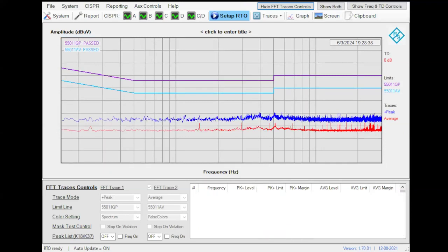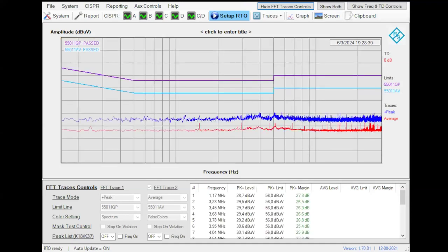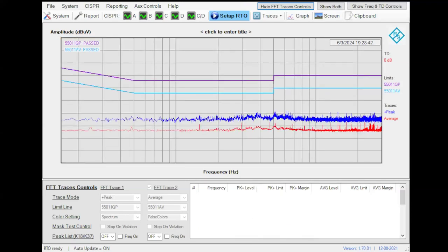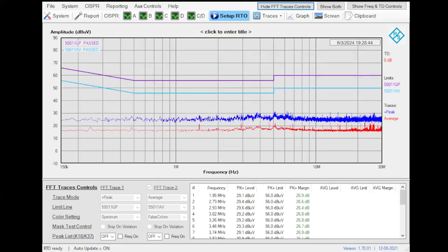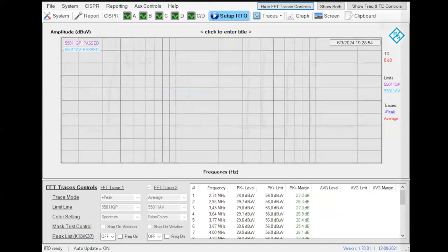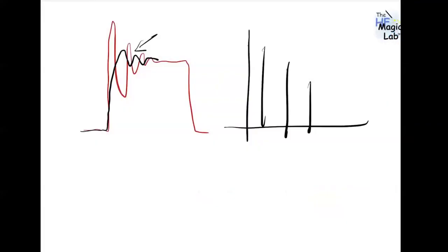A snubber probably is a good option when you have something that does some kind of ringing. If you introduce a snubber, you can reduce the ringing. But usually the harmonics you are experiencing in some specific frequency range are related to the square wave signal in the switching node voltage.